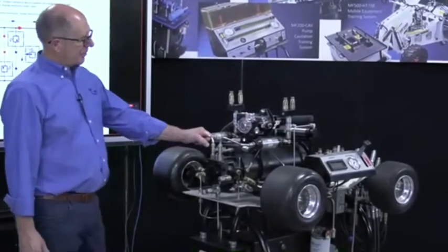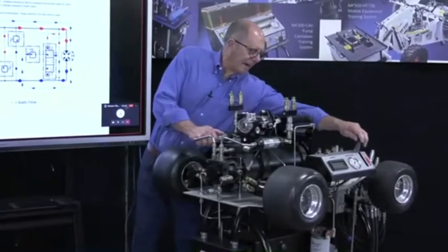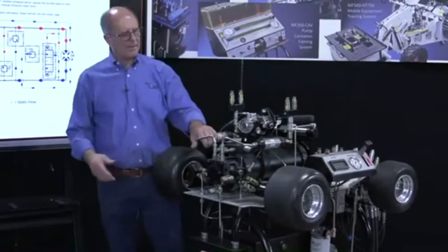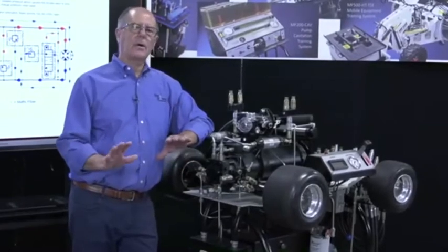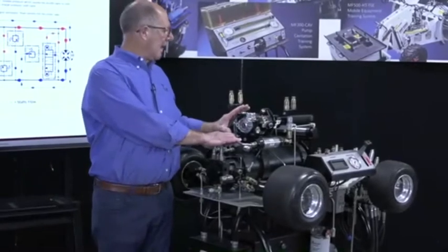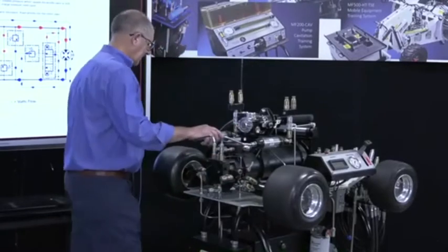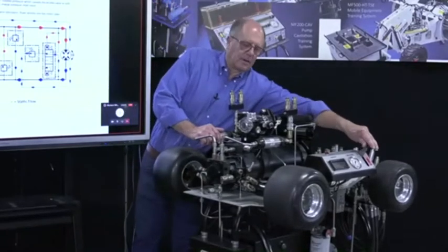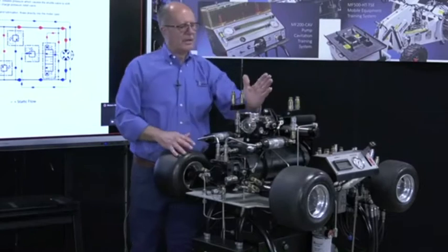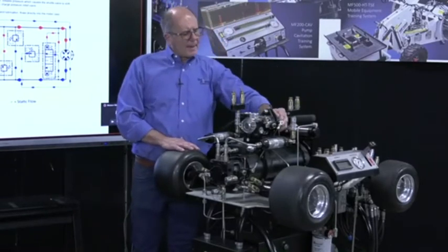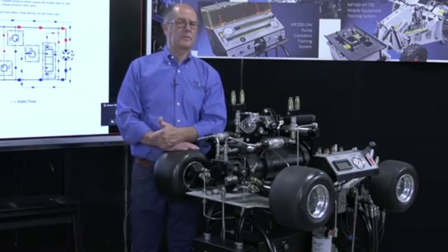Some students have difficulty figuring out what is actually happening when I move the forward reverse control lever backwards and forwards. What's actually happening in the unit itself? Well, to make that really clear, we buy two identical pumps and we cut one away in amazing detail. Then we put it just above the main pump and link them together so they operate in concert. If I move the forward reverse control lever, I'm not only operating my main pump, which is turning the wheels, but I'm also operating the pump above. So not only can the student see how the swash plate is moving and going over center, but since it's an axial piston pump, I can also rotate it and see how, when I go over center, it causes the flow to reverse.